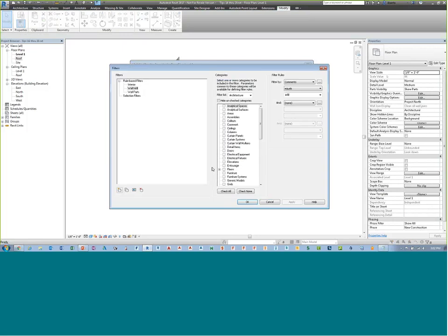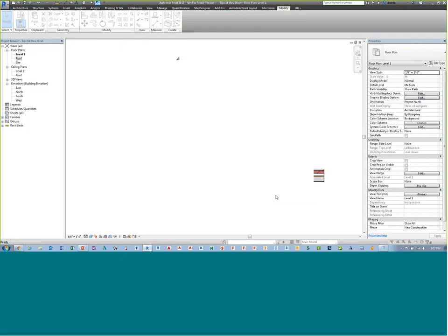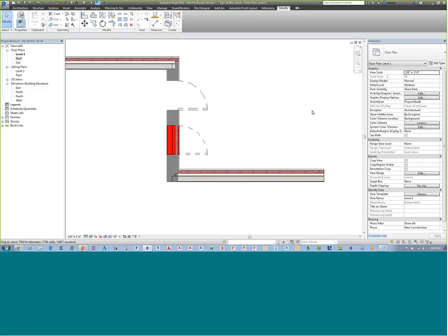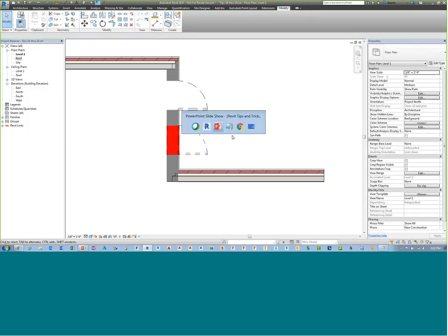Again, looking at the properties of wall infill, and it's looking at walls. And if the comment equals infill, then apply the filter. And that filter basically says, I see it or I don't see it. If it's unchecked, I don't see it, and they disappear. So this one over here, I go in here and I type in infill, it disappears. Okay.